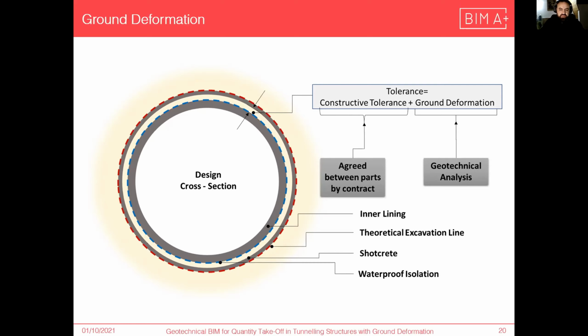But in real life, after the excavation and the shotcrete, the deformation will happen, and then we cast the inner concrete, so there's no void in reality. But this is a representation of two conditions at different points in time in the same model in order to measure the correct excavation and shotcrete quantities.